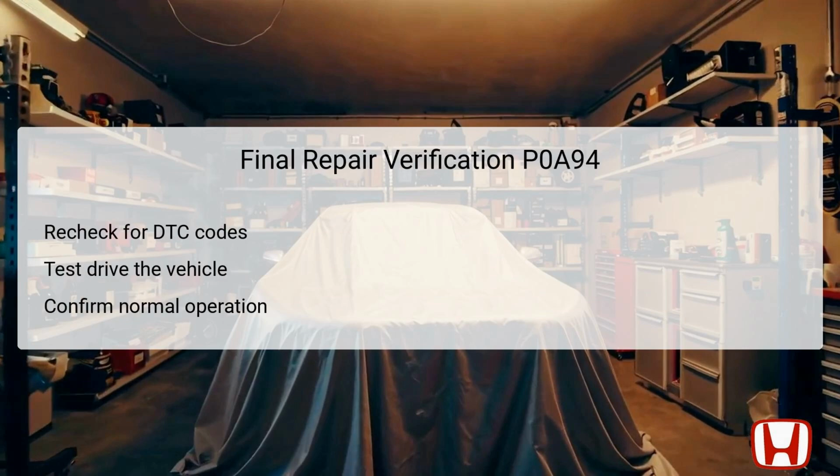After repair work related to DTC P0A94 is completed, it is crucial to conduct a final verification to ensure all issues have been thoroughly addressed. Start by rechecking the vehicle using the Honda Diagnostics System, HDS, to confirm that no DTC codes remain active. This step provides immediate insight into the system's current state following repairs.